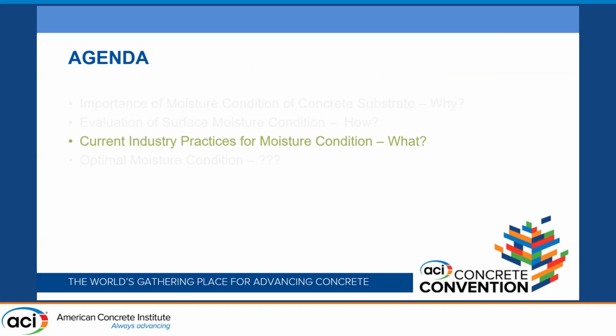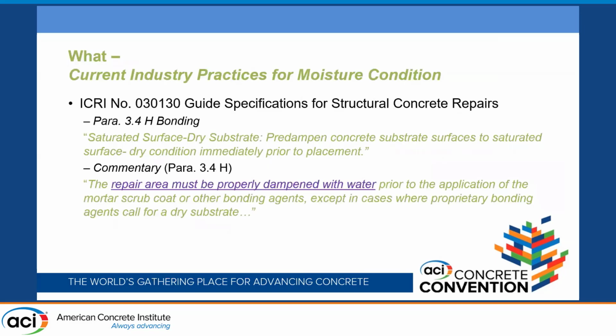So what is current industry practice for moisture condition? We've looked at ACI and ICRI guideline documents. The only one that talks specifically about surface preparation regarding the moisture condition is the ICRI guide specification for structural concrete repair. Paragraph 3.4H, Bonding, refers specifically to saturated surface dry substrate and talks about pre-damping the concrete substrate surface to SSD immediately prior to placement.